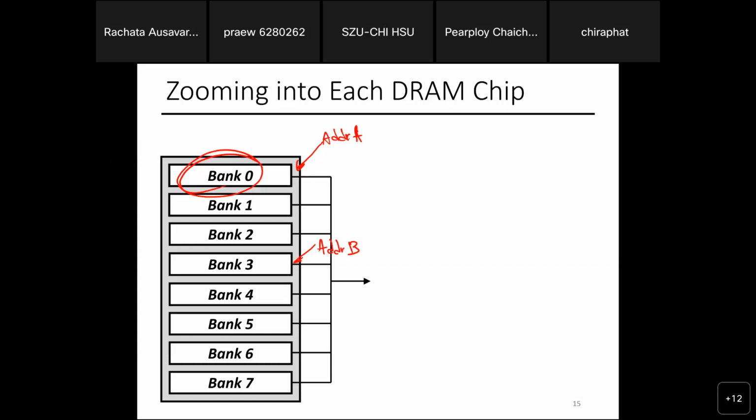And it's just because the chips are smaller, each chip sends, in this case, let's say 8 bytes of data. How big is your cache block in the Intel CPU? 64. If I send out 8 bytes per chip, can I just use 8 chips to send the whole cache block in one cycle?